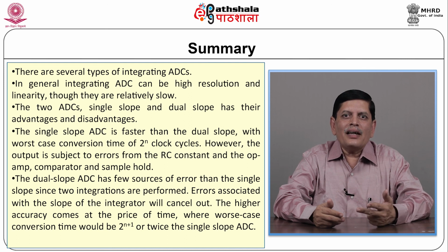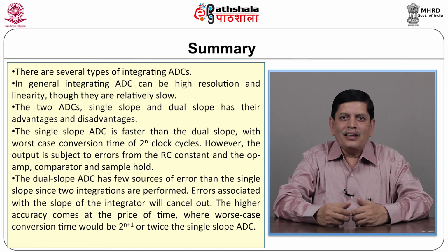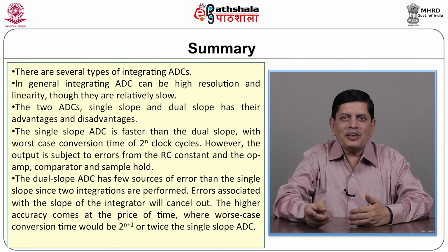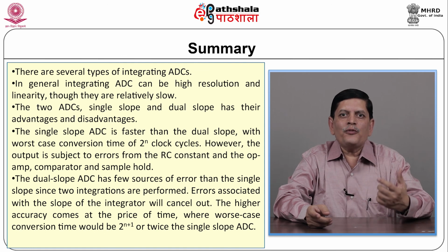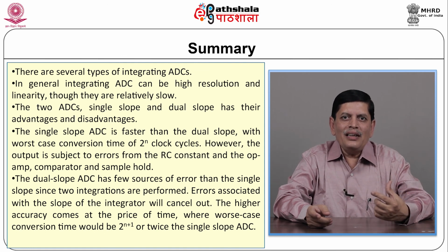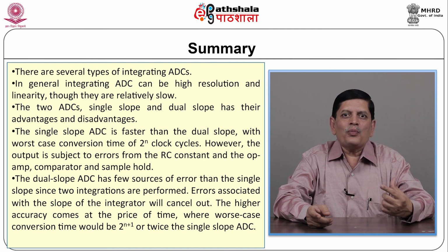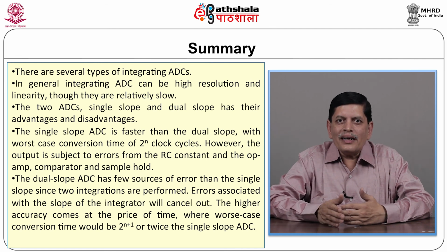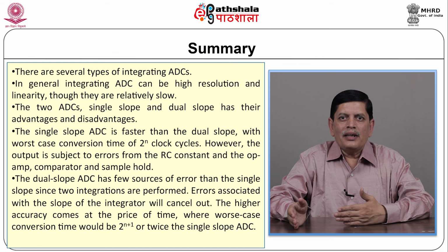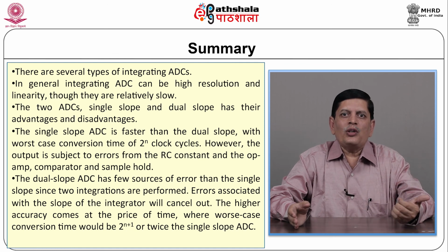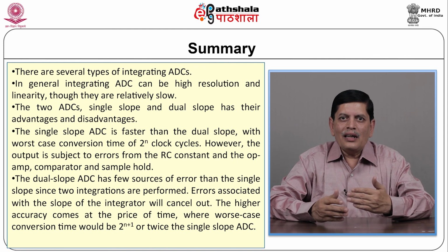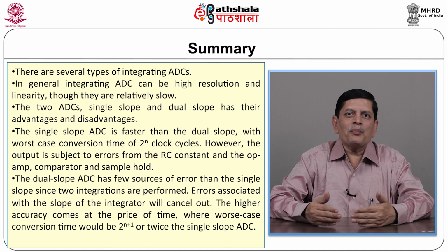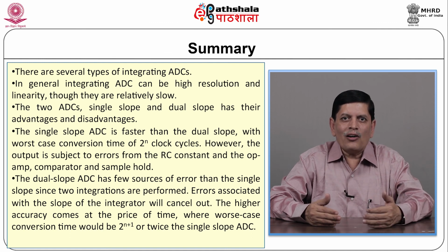Basically, the ramp generator is an operational amplifier based integrator circuit. The charging and discharging time of the capacitor is used. Whenever we discharge the capacitor, it is always with reference to a reference voltage. So, naturally there is no question of a variable slope; there is always a fixed slope ramp that could be generated, and therefore, the output digital count is independent of whatever input voltage we apply. So, naturally the advantage of dual slope ADC is that it is error free, it is not dependent upon whether the input varies in between the recording or not.